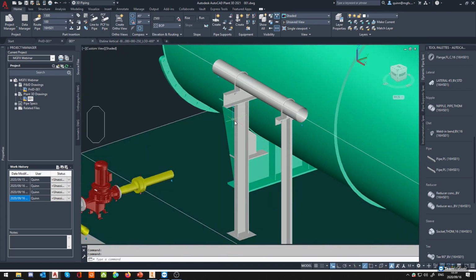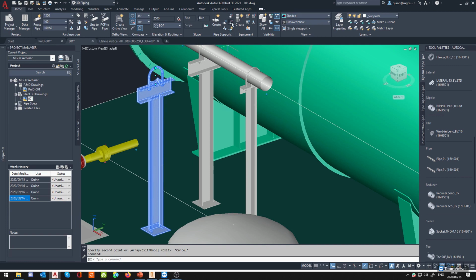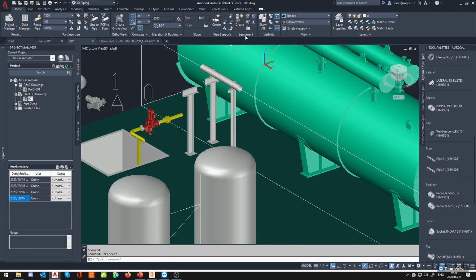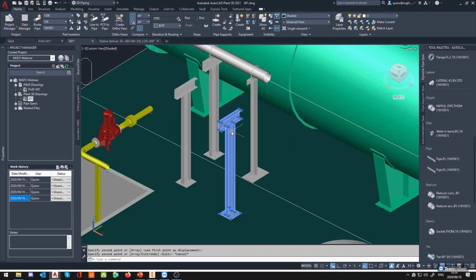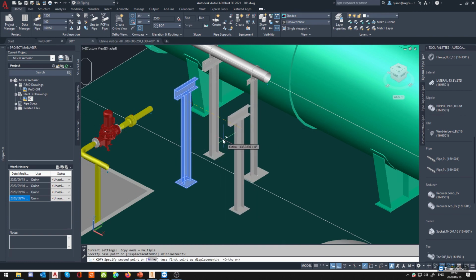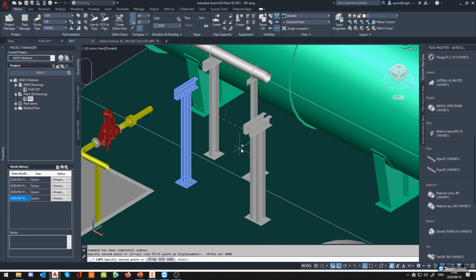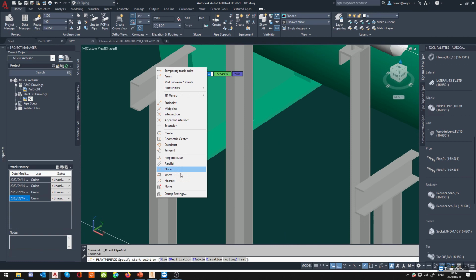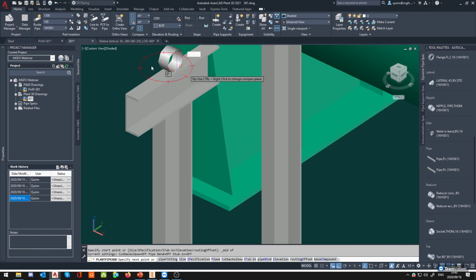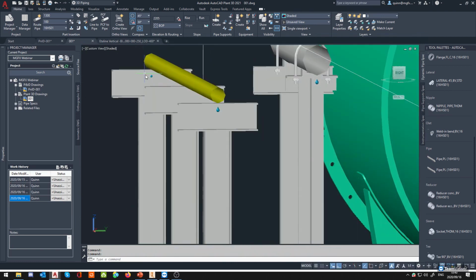So in other words, if you had something like what I had over here, I was attempting to show over here, and if I had this little pipe, I'll explain what I was doing there in a second. What I could do is I could have an array of these, like that. Then just move it over a little bit. Could have a whole array maybe, and then route my pipe directly on top of here. And that way I know that my pipe is running directly on top of maybe existing pipe racks that you're routing on top of, or other walls or something like that.